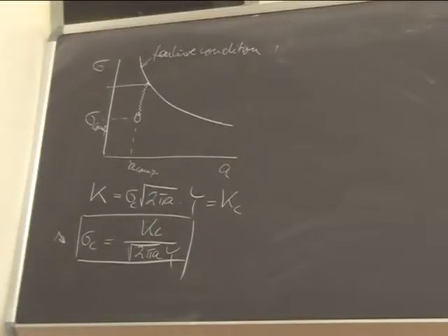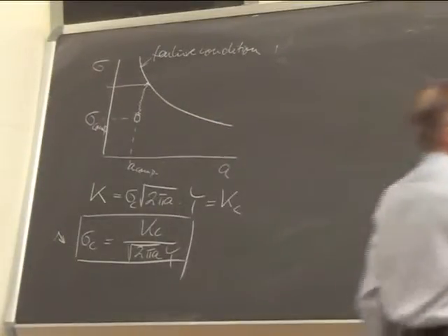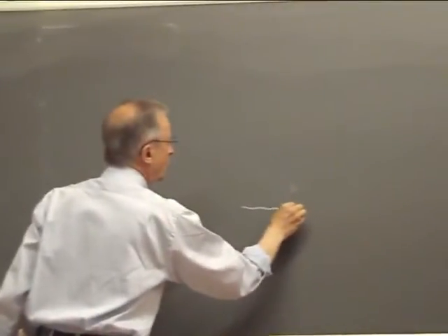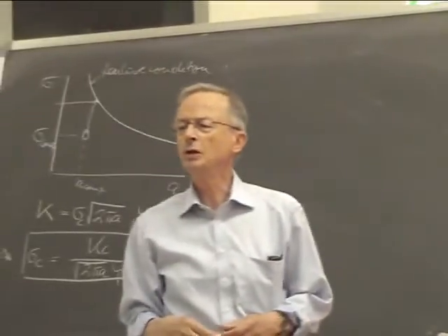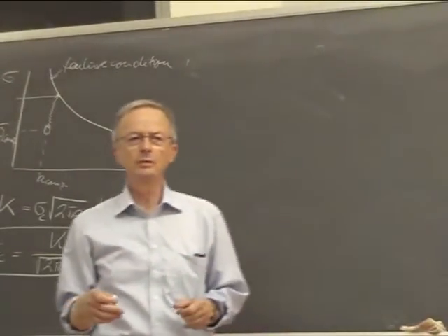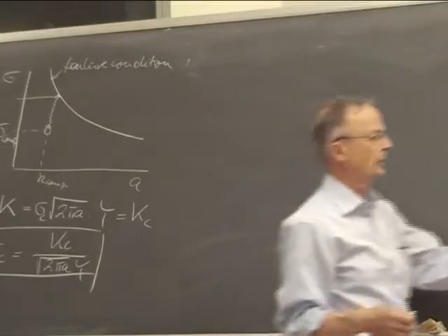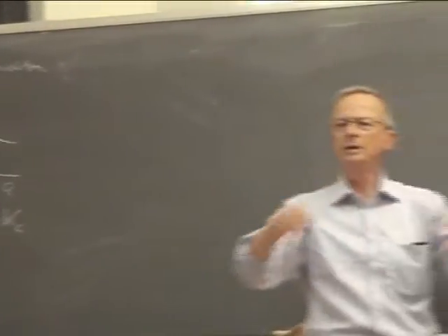Or a popular method, by the way, is when you have a crack, you drill a hole into the crack tip. So you drill it away, you machine the crack tip away, and either the crack stops forever, or it takes some time until it reinitiates, and so you gain life. So this is a popular trick.